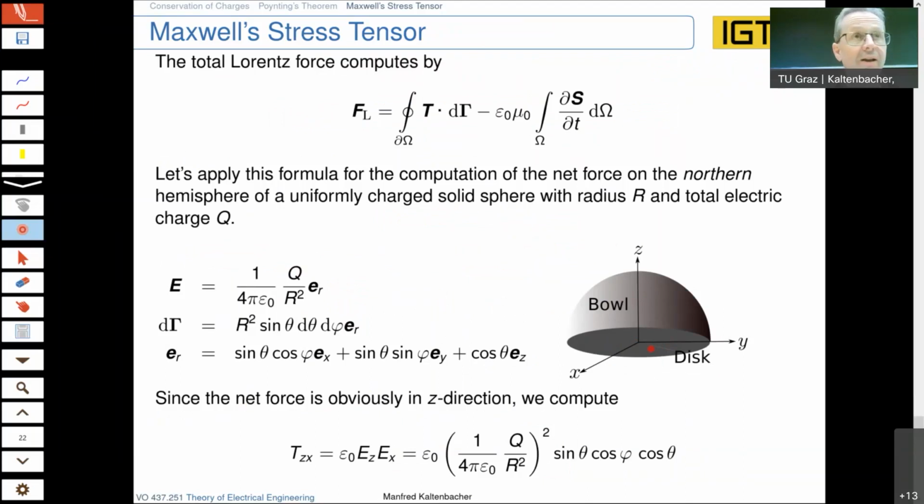And there you will see that this is really complicated in an analytic form to apply the Maxwell stress tensor, and it's clearly easier with the Coulomb forces as we have learned. Anyway, you will see that you come up to the same procedure, and in any numerical program it makes more sense to use the Maxwell stress tensor because it is a straightforward procedure for implementation.